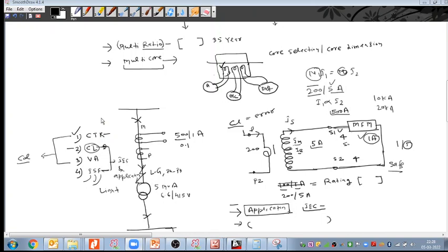In that case, the CT will not be able to generate the required power, Raghunath. It is the same as taking a 2 MVA transformer and putting a 3 MVA load on it. So what will happen? The same you can take here also.